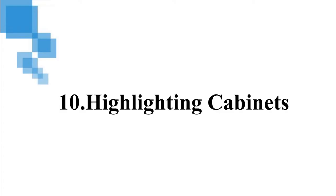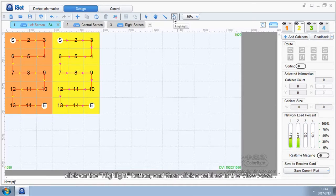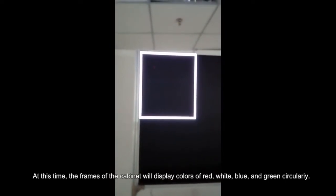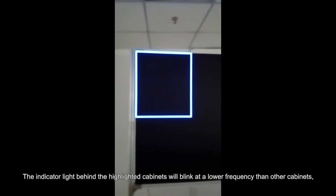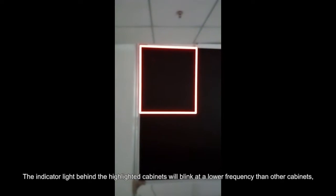10. Highlighting cabinets. We can highlight the cabinets in iSet. To locate the position of a certain cabinet, click on the Highlight button and then click a cabinet in the view area. At this time, the frames of the cabinet will display colors of red, white, blue, and green circularly. The indicator light behind the highlighted cabinets will blink at a lower frequency than other cabinets.